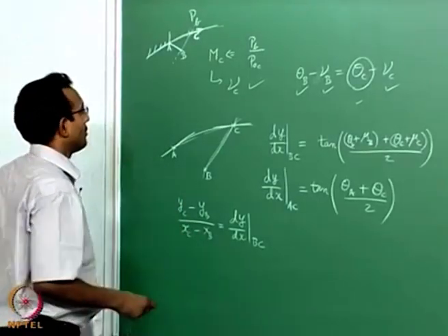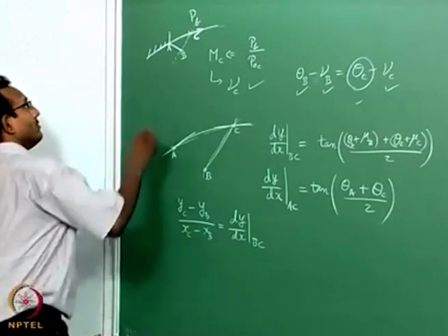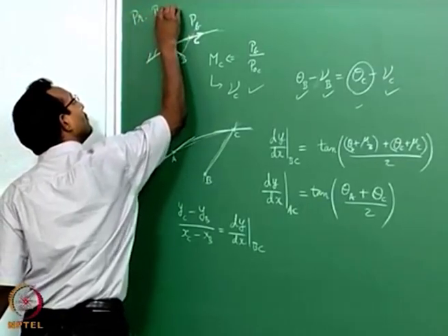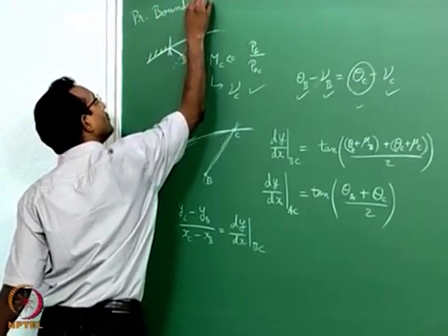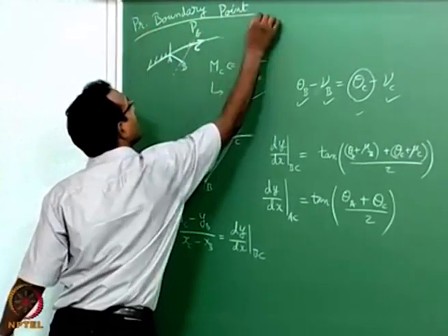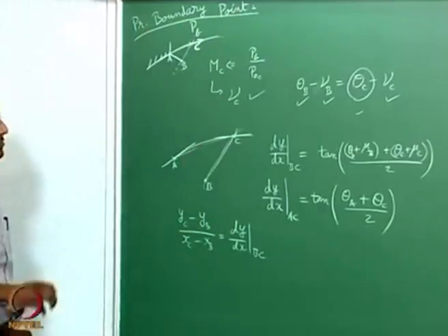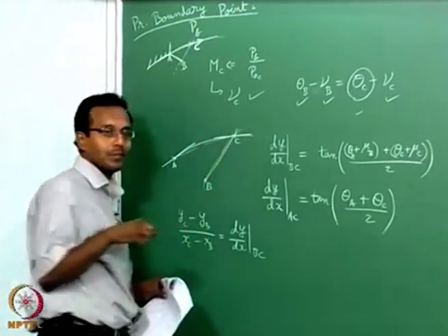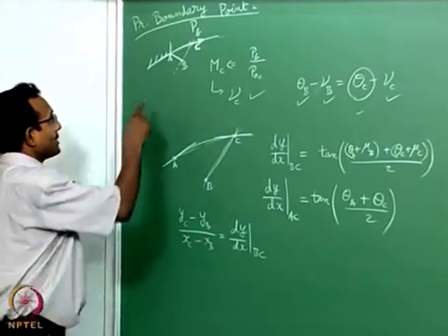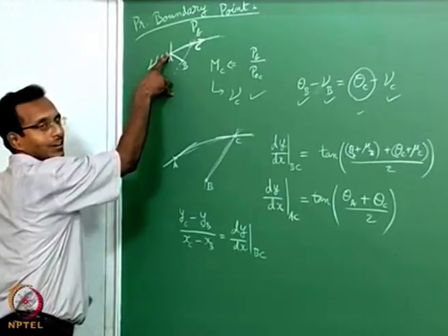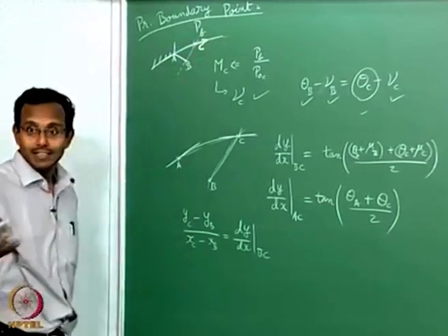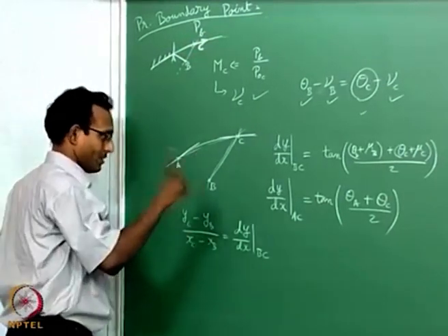Okay. So we have another routine now, which is what I call a pressure boundary point. That is, I am finding the values of x, y, theta and Mach number for a pressure boundary point. Now that being said, I actually did it from a wall corner to a pressure boundary. Will it work from here to another point? Yes, it will, because I will draw that separately.